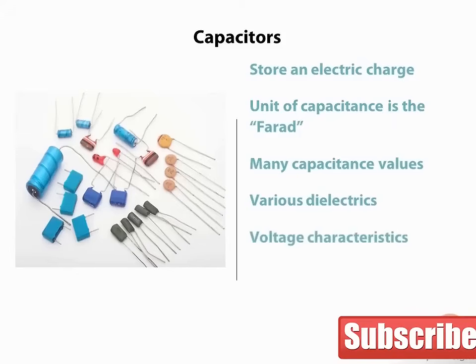Just as resistors have to be selected with adequate power ratings for the application, so must a capacitor be selected with adequate voltage rating. You need to be aware of the maximum voltage that the capacitor may see in the circuit and select a capacitor that is rated above this voltage, and with an ample safety factor. Selecting a capacitor with too low a voltage rating will destroy it, and sometimes with great fanfare, which can be dangerous.